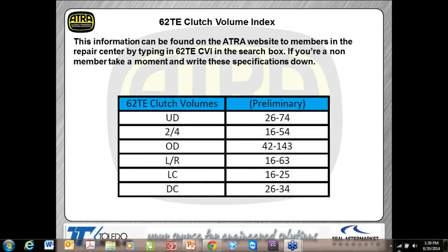If you're working on a 41T, you won't find any ID marks, but what you do have to take a look at is one side of the pump gear itself, on both of them actually, will be a chamfer that's much greater on one side than the other. Now that chamfer is not your ID mark. That chamfer actually has to face down because they want to hold lube in that pocket for the pump gears. So the chamfer side, the much greater chamfer side, has to face down. So make sure you do that on that unit.